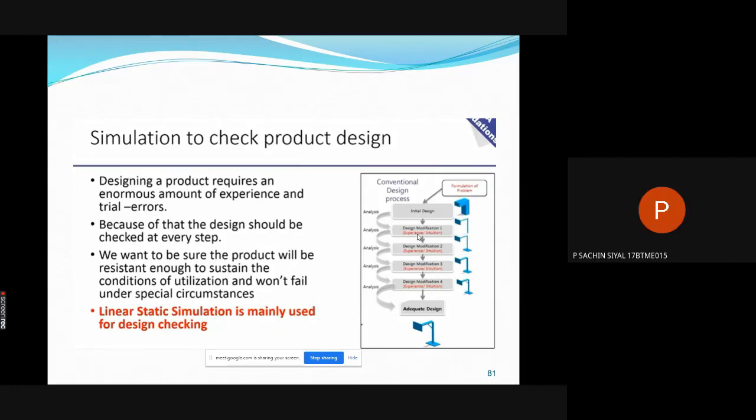Can you repeat the question, sir? See, the yield stress of the material is 270 megapascal. If I use the first model given by the product design engineer, apply the boundary conditions according to the customer's needs, and check the stress induced inside the material, I get around 0.04 megapascal. So what is the meaning of this? Yield stress is 270 megapascal. It can't take the desired load, no, sir. If at the start itself it has this much load it can take, it should be designed on the basis that it can withstand that amount of load. Yes, that's only what I'm telling you, Sachin.